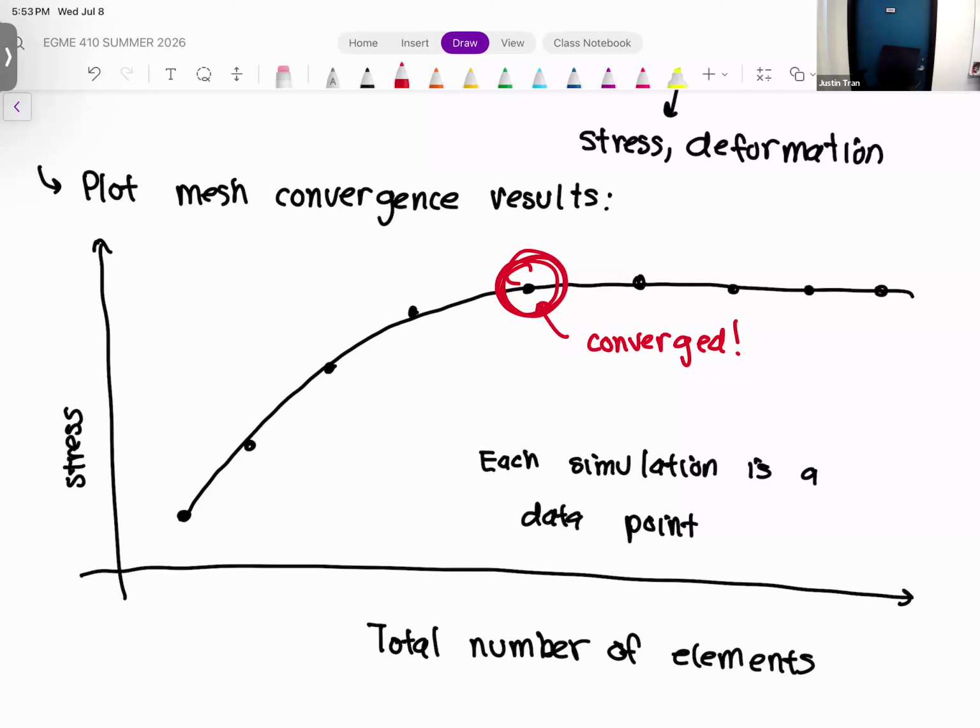Okay. For the midterm, for example, what are the different types of refinements? Well, I think we talked about it too. Yeah, when I talk about refinements, practically you're going to be doing an H level refinement, which just means making the elements smaller in a particular region. Technically, there's P level refinement too, but like I mentioned, if you're using ANSYS, quadratic is the way to go, because there's really no reason not to use quadratic since ANSYS makes it so easy to do that.